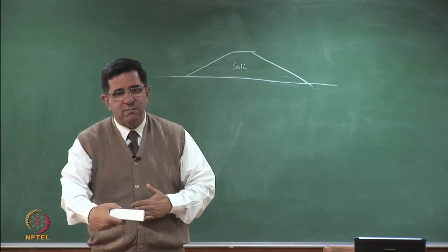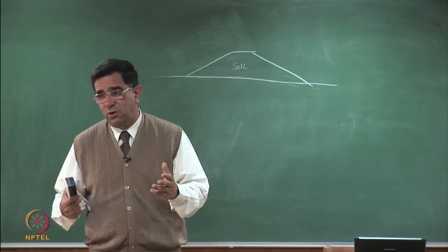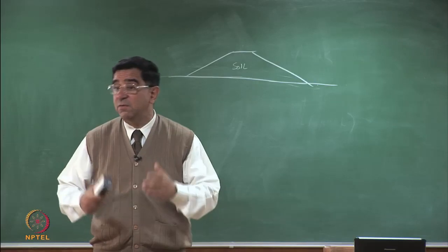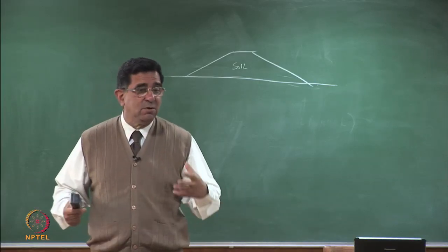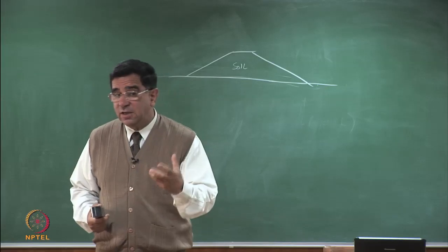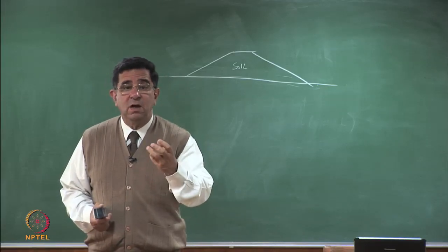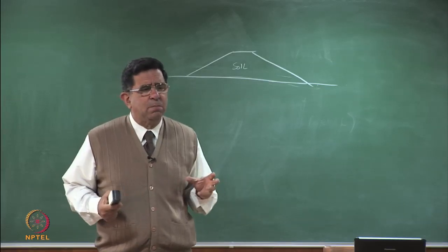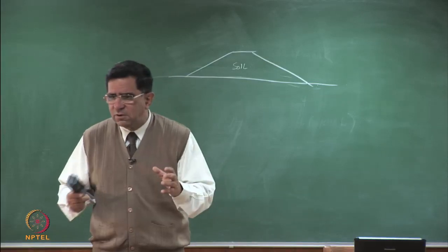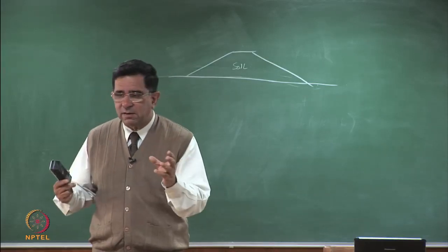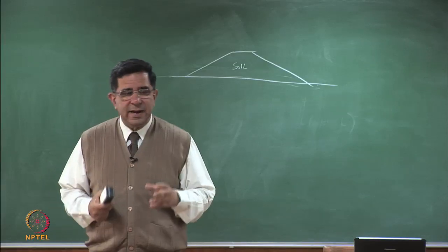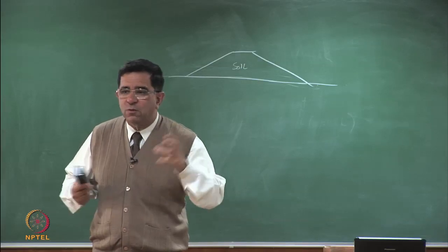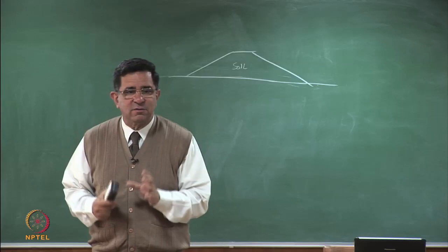Well, 1 foot by 1 foot may not, it depends on the size of your rock fill, but you could have 600 millimeters by 600 millimeters or even larger. So here also, if I am using waste which is heterogeneous, the size of the direct shear box will depend on the size of the largest particle. But if there are only 1 or 2 large particles and others are relatively smaller, then I can remove those particles, because my shear strength parameters are not going to be governed by 2 or 3 or 4 or 10 large particles. They will be floating in a matrix of waste.